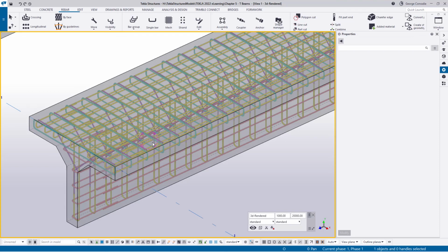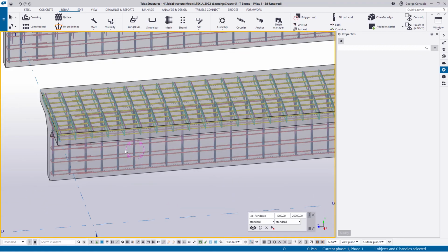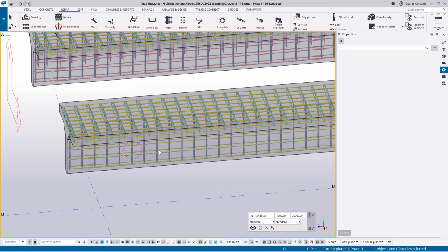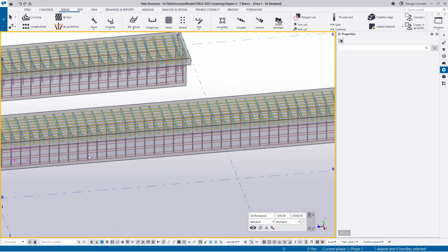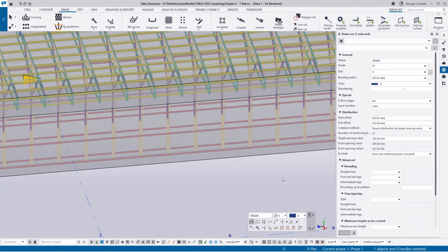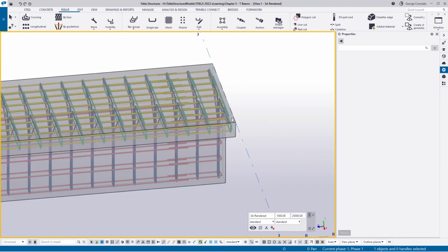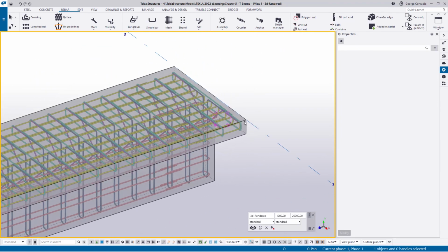if you do have alternate lengths, if you've made them exact, it will impact the length, because you're now really restricting the number of bars you want to create. But in this case, it's very easily done. We can just go through that same process again of making this the primary bar, fixing up the spacing, and then resetting the others to get it clash free. So I think it's pretty good in that regard.